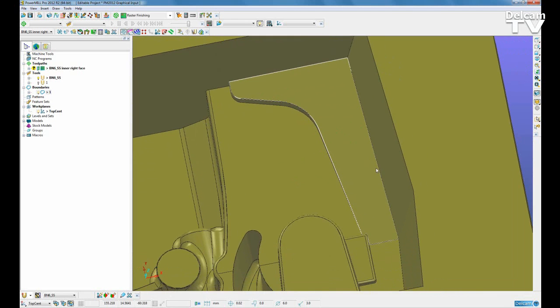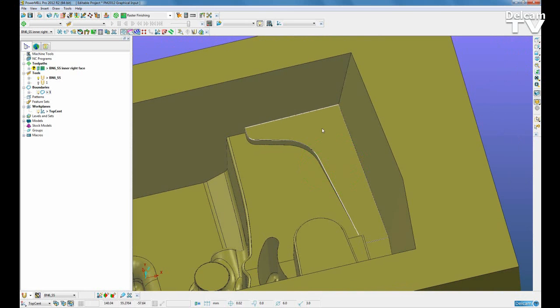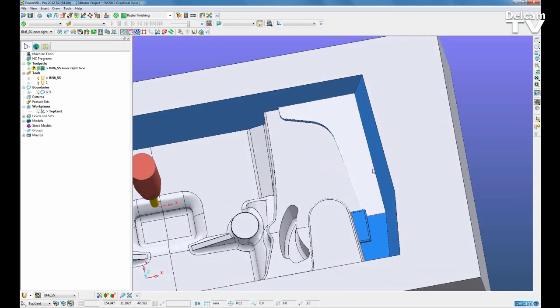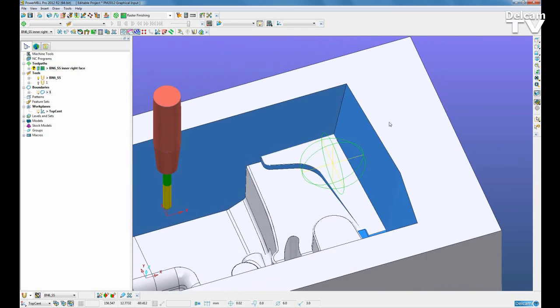In so doing, I want it to be at the angle that is shown on the front edge. I have previously set collision avoidance on these surfaces and the side to ensure only that top face is shown. The blue surfaces will not be machined when I create my machining toolpath. Only this area indicated in white at the top within the boundary.